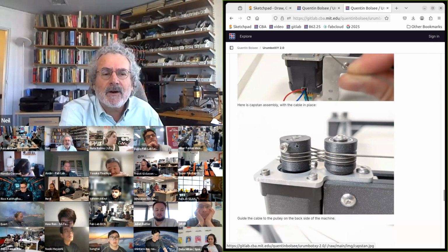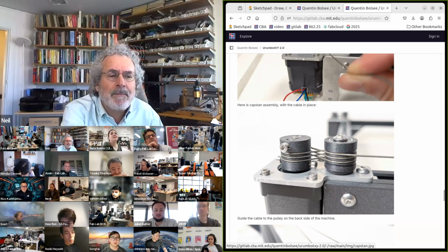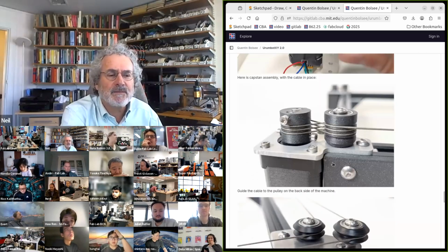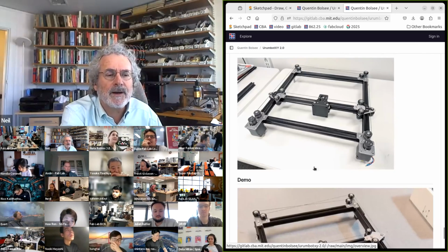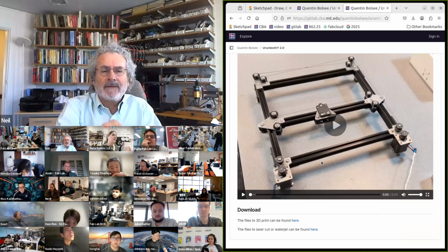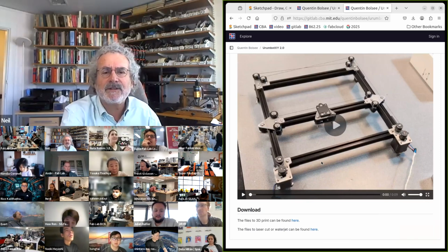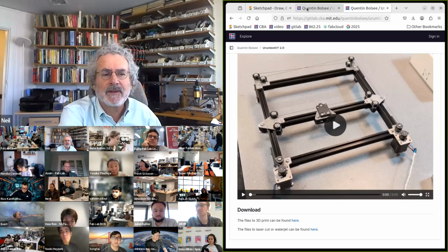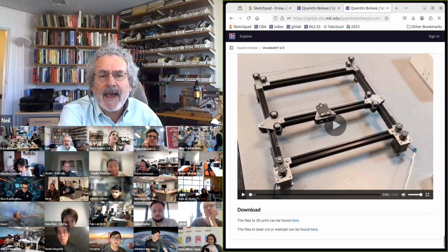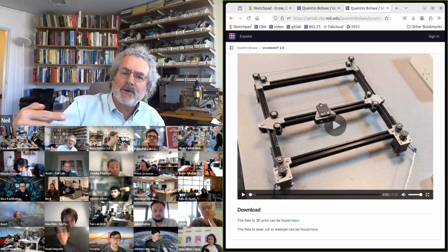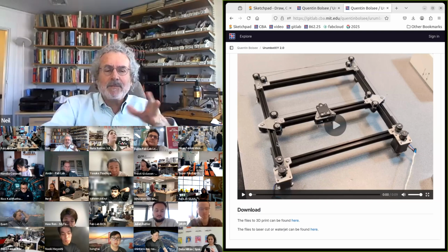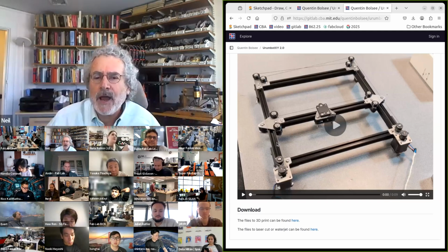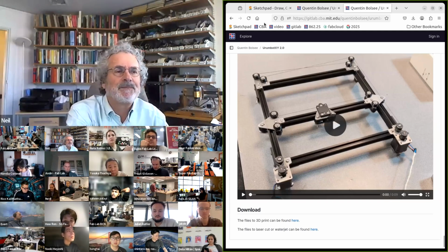But it could slide on the drive motor. And so the wrapping under tension around the idler significantly increases the friction, so much so that when you've made the machine, you can't just displace it by hand. It's constrained almost as tightly as the timing belt would be. These capstan drives are a really good approach for force transmission, because this could be any shape you want. It could be linear or rotary, long or short, and you just wrap the filament for whatever shape you want for the machine.